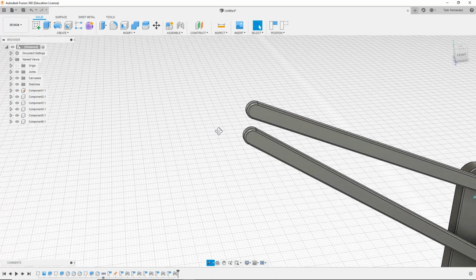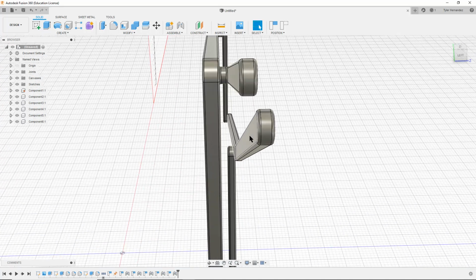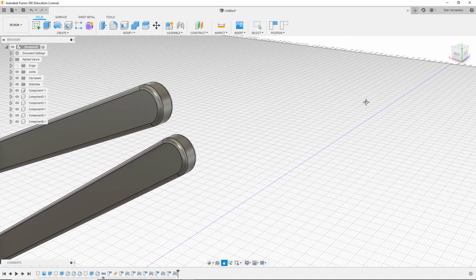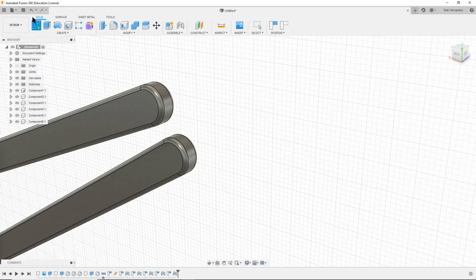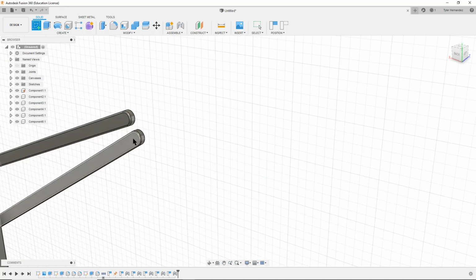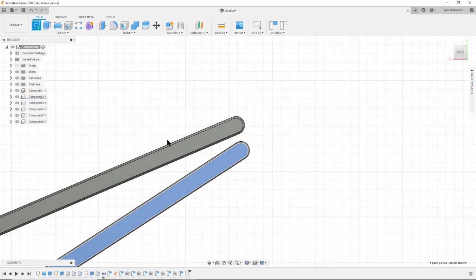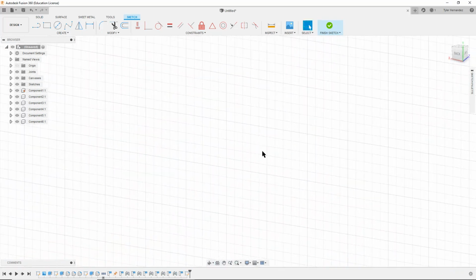So in order to do that, I'm actually going to make this piece a little bit bigger. And to do that, I'm going to select the end back here and extrude it back so that it is in line here. And let me show you what I mean. Let me rotate my camera. I'm going to go to Create Sketch, select, I'm lagging a little bit, select this face, capture position, and oops, let me zoom out a little bit.